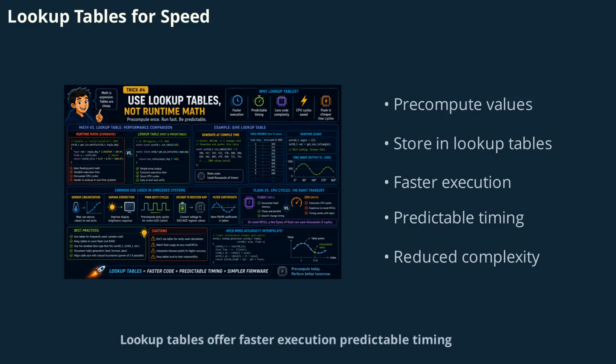Lookup tables offer faster execution, predictable timing, and reduced code complexity. While they consume flash memory, flash is often cheaper than CPU cycles. Use lookup tables to optimize performance and simplify your firmware.